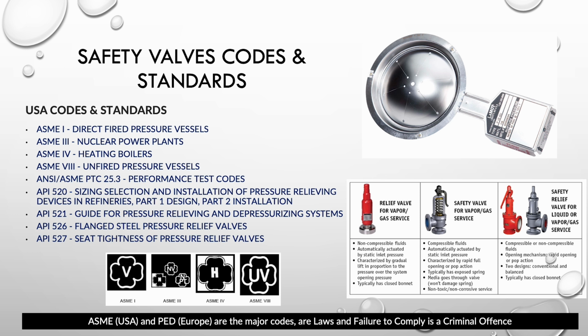And the reason I was kind of joking with Mo, and it's a favorite topic of mine, is I see more issues with this than with a lot of other things, as far as valving goes. Just throwing it out there: if you have the ability to isolate your relief valve, then you don't have a relief valve. If you don't actually know what your relief valve is doing, you don't have a relief valve. If you've never verified that your relief valve is in good shape, you don't have a relief valve. And there are some places where you need a relief valve and you don't have anything.